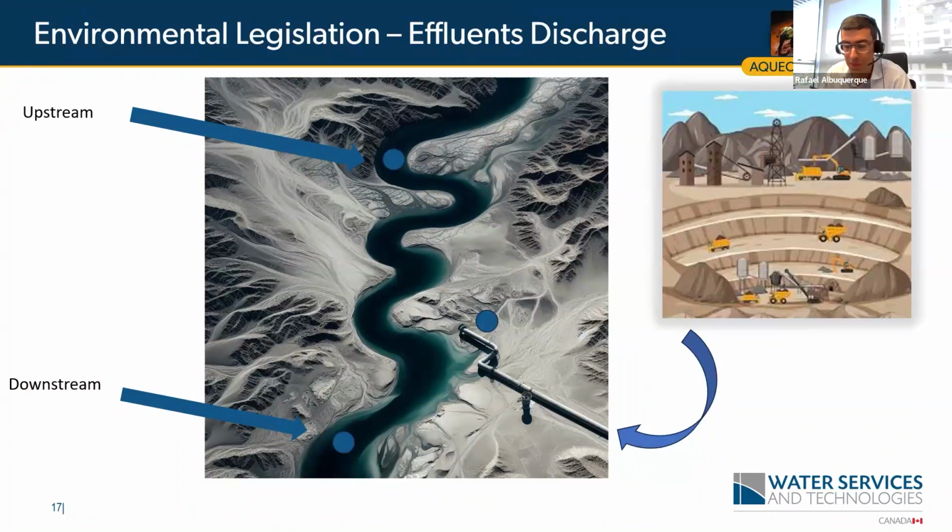So basically, what we should attempt, if we have to generate effluent from the mine site, is to generate effluents that have concentrations that are not going to violate these standards, right? And usually we'd also like to monitor upstream in this receiving stream, because anomalous concentrations may be related to external factors like geology, or contamination from a neighboring operation, and so forth, right? So this is something very simple to understand technically, right?